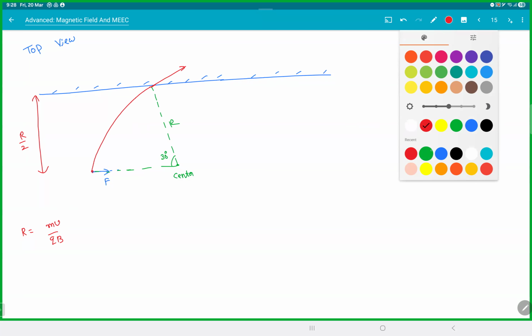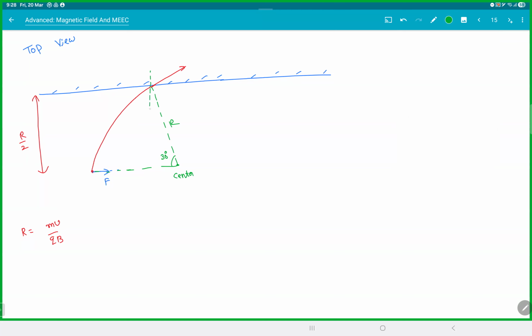Now this is the velocity here. That should be tangential. This is the normal. This is 90 degrees. This is 60 degrees. Right? And if that is 60, this whole thing is also 90. So this is also 30 degrees. Perfect. Be careful with it. That means the particle is hitting the wall at 30 degrees, not 60. Just have to be careful with the geometry there.